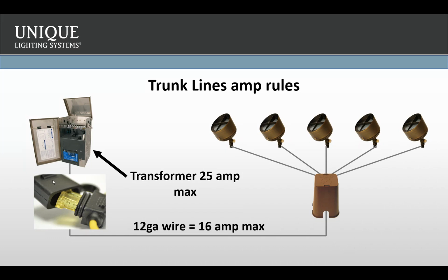too many times that I can count where I've been out in the field. The system's been in the ground for a long, long time, and suddenly all the wires right here at this location are burning up, and then I'll get the question of, well, why didn't your transformer trip? Well, that's because the wire burnt before I could get to the max amp rating.